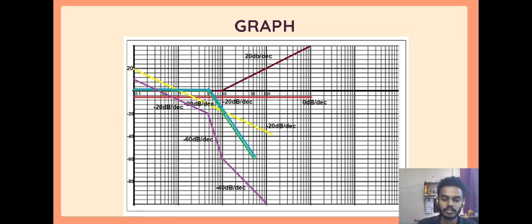However, this immediately cancels out by the pole at the same frequency, resulting in a flat gain response in the region. We reach omega equals 5. The two poles begin to influence the slope. The first adds negative 20 dB per decade, and the second adds another negative 40 dB per decade, making the total negative 60 dB per decade beyond this point.